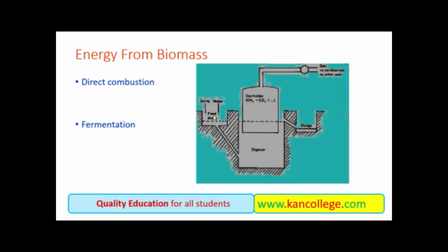A mixture of dung or manure and water is prepared over here, and that is sent into the main well for some days. After some days, the process of fermentation produces methane gas and carbon dioxide gas. A heavy cap is placed over the well, which collects the methane gas and directs it to the utilization media.